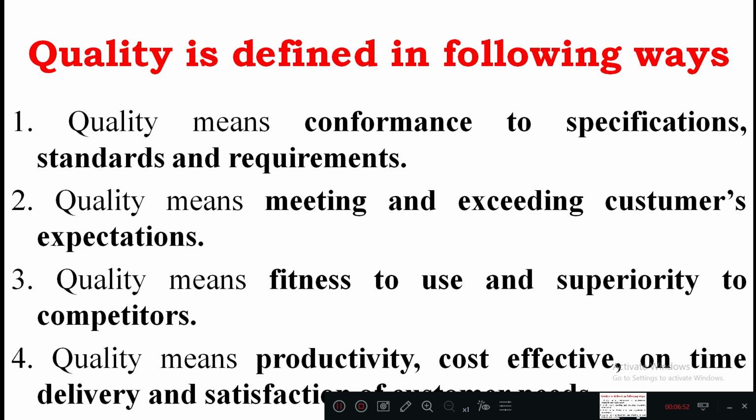For example, you need to construct for one day only 1 meter of brickwork. And if you are following different types of bonds, that is English bond, Flemish bond, and so on, certain procedures they have mentioned. So as per their specifications itself, we need to construct that. And with respect to the materials, they will be mentioning even the chemical compositions of the material. Yes, this brick should have so and so percentage of silica, so and so percentage of lime, etc.